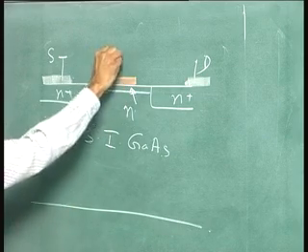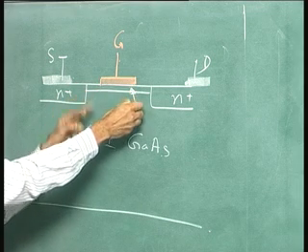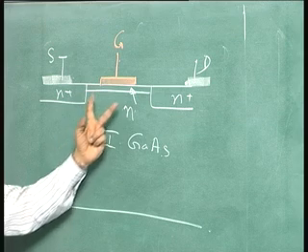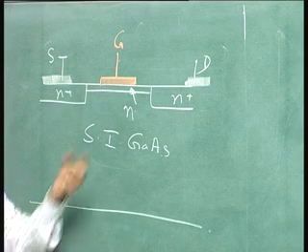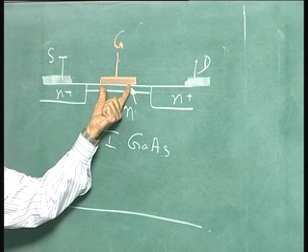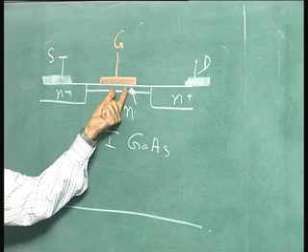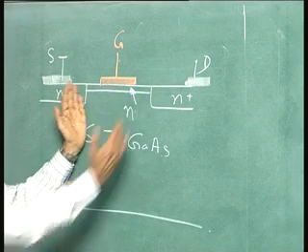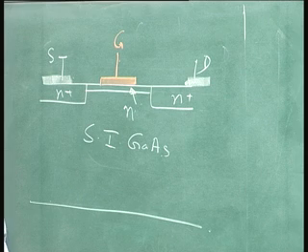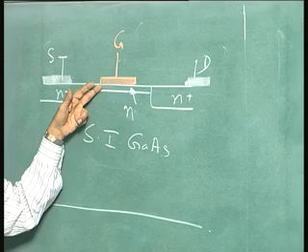That is the gate. That is the LG gate length, and this is the gap. So, what we do is, in one set of experiments, we keep this gap at 0.3 and reduce this gate length, which means when you reduce this, if you keep this gap same, that is reduced. For a given drain to source voltage, the fields are higher. Notice these fields in this direction are higher.